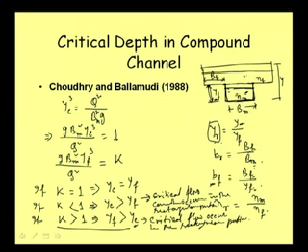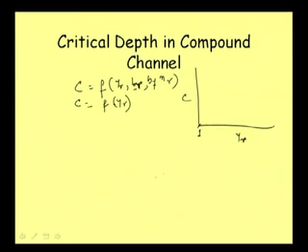So, when Y is equal to YF, the depth of flow is this much, we are getting it below the rectangular portion. Now, we are interested when it is above this. When Y exceeds this YF, then YR becomes higher than 1. When it is higher than 1, we are interested in what will happen, and then we are talking about this term C.